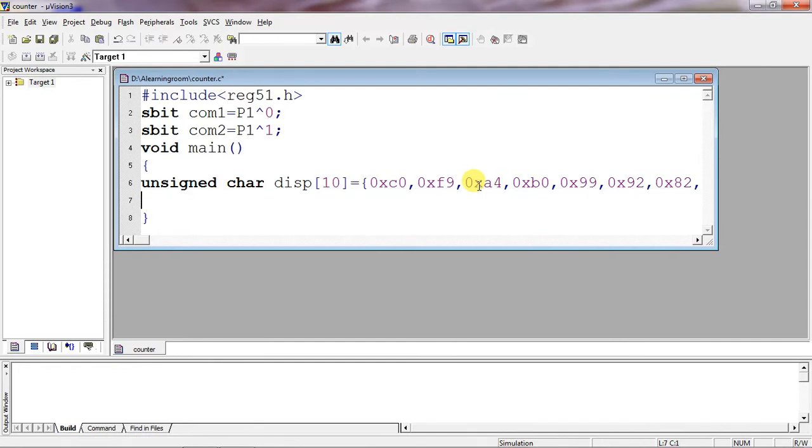And you have to follow the steps related to the counter. By using the TMOD register, and you have to write all SFR registers in capital letters in an Embedded C program. You have to assign the equivalent value to display 00 to 99. I can choose mode 2, and now I am selecting counter 1 in mode 2. So the equivalent value is 0x60.